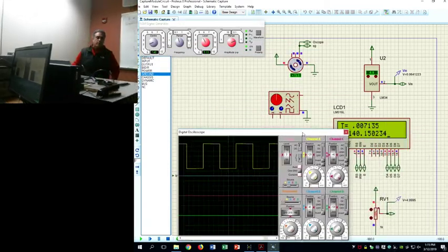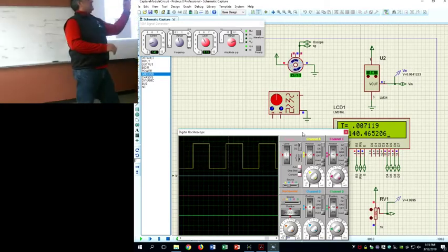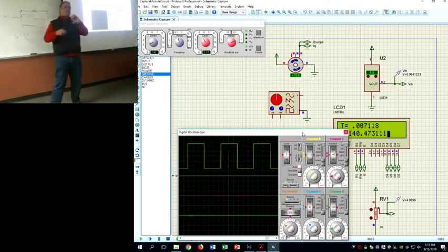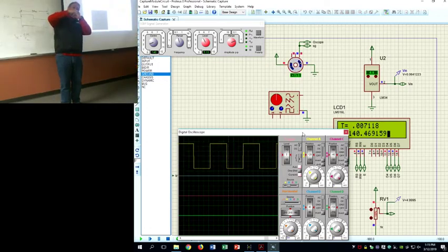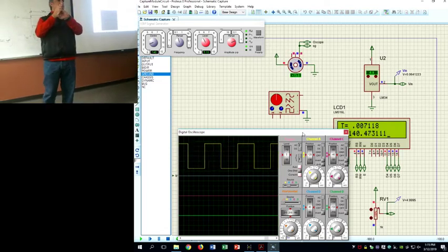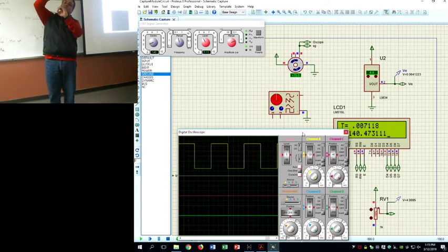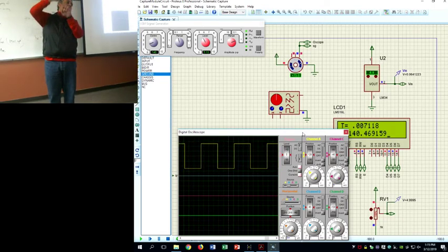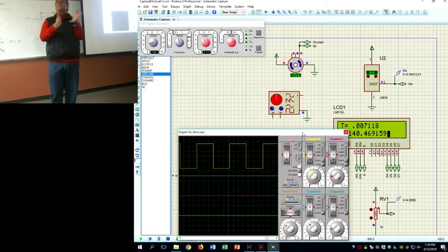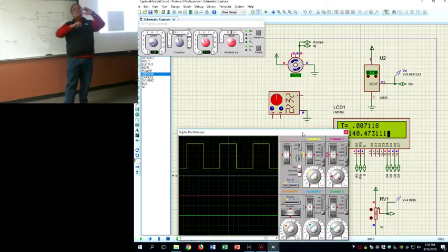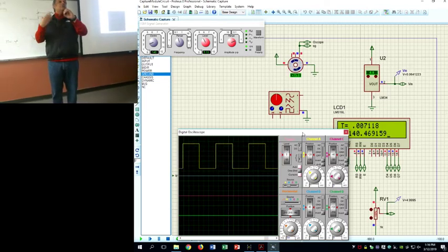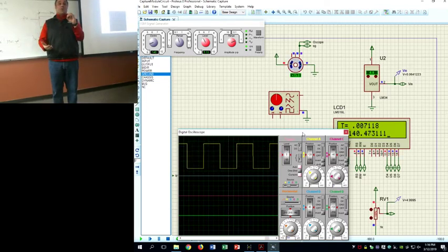So while that motor is rotating, what these guys do is take the shaft of the motor, and there are all kinds of different means by which we can do this. One of them is a little sticker that goes on the shaft itself. It has little reflective surfaces that are created with a laser. You put a reader on it, and as the shaft is moving around, the laser gives me shiny spots and dark spots. Sometimes they put 150, 160, 170 of those spots on the shaft. So every time the shaft goes around, I can see 161 pulses coming from the motor.